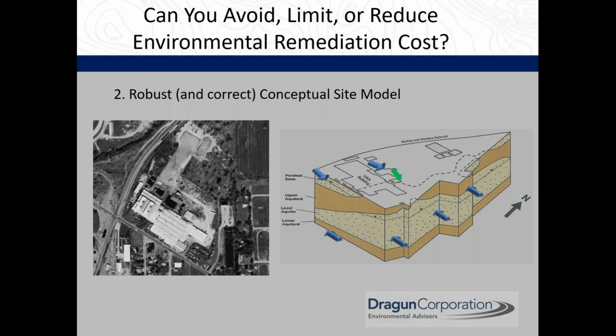So they totally misinterpreted the groundwater flow direction, which they had going from west or left to east or right into the subdivision. And because they were totally different aquifers, they came up with a tremendous velocity and contaminants moving towards the residential subdivision in the east. So this was not a good situation.